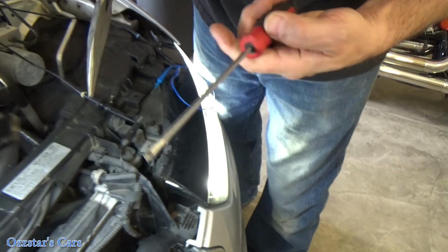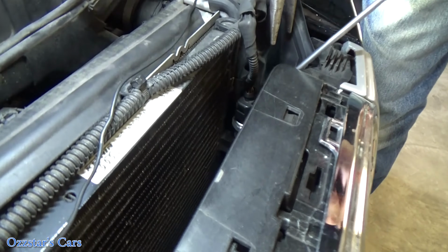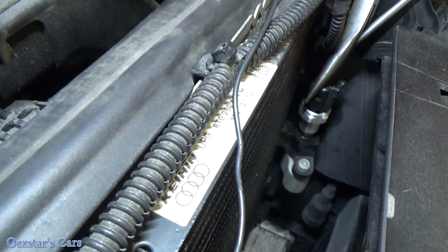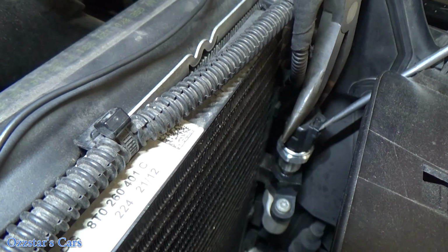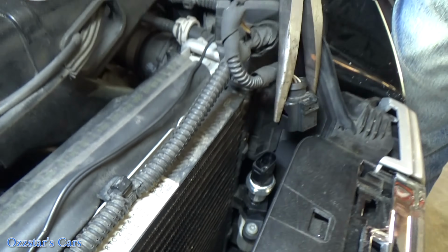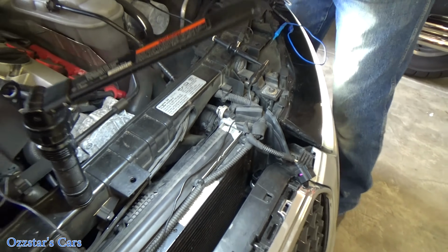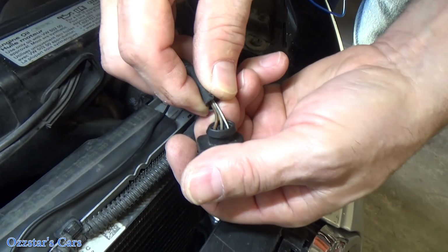So what I do is I take a long flathead screwdriver and some long needle nose, and basically I grab onto the connector, not very hard, just giving it a little bit of squeeze, and I'm pushing in on this tab while I wiggle and pull up, and I made that look easy. So your first time, it probably won't go that slick for you. But anyway, here's our 3 pins, and there's our 3 wires.